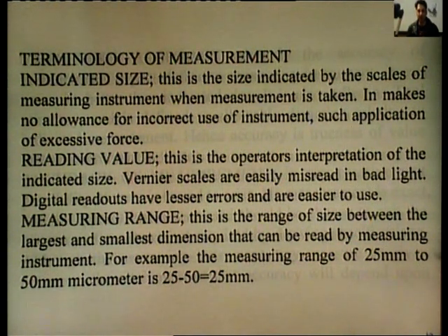So, the indicated size is the size that the instrument is indicating for the component, but over here if we use excessive force, the instrument will not give the right reading. So, there is need for a lot of care to be taken while using these sensitive instruments for getting the right value, that is the accurate value or the true value.